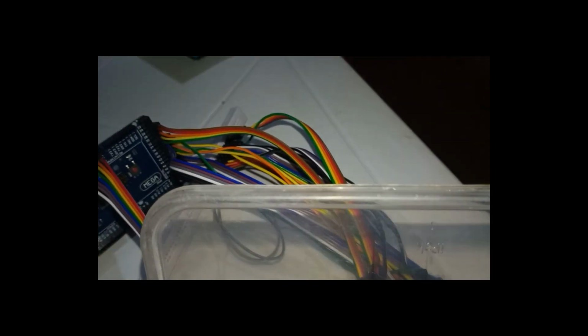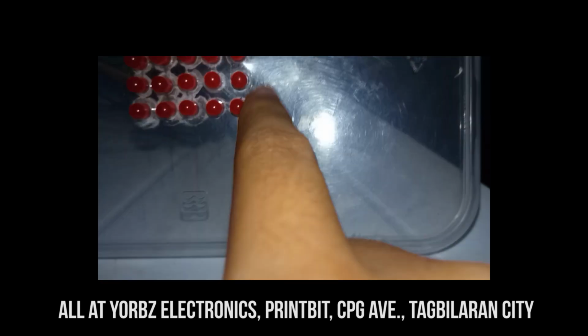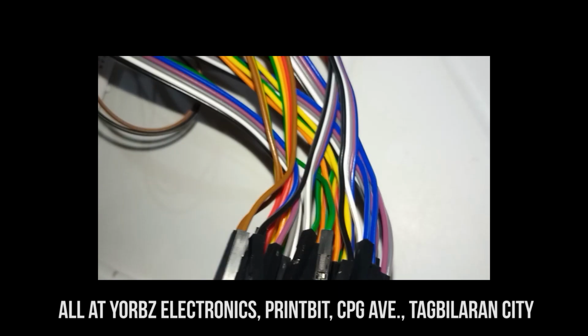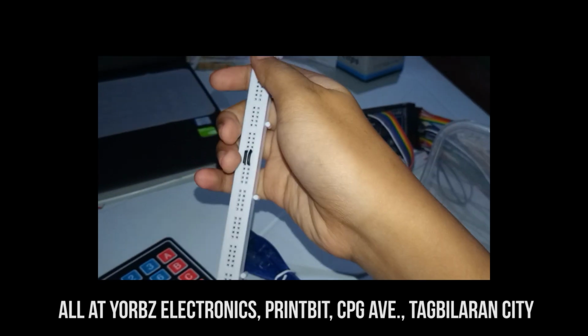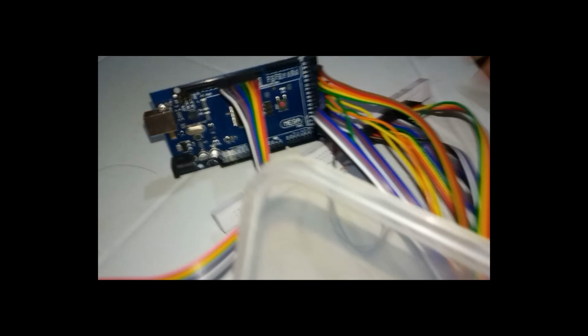50 male-to-female wires, or female-to-male wires, because we are using this one also as the output, 5x5 LED lights. As you know, an LED has 2 feet, the positive and the negative. So we're going to be using one female-to-male wire for the positive and one female-to-male wire for the ground. And we use this part of our breadboard. This is connected horizontally, for all those who may not know what a breadboard is and how it is connected. So we're gonna use this as a ground.